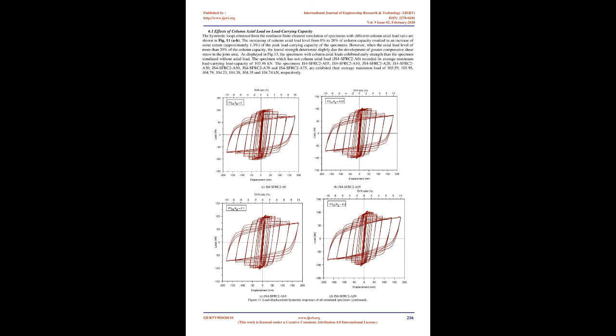Note, P is the applied axial load to the column. f'c is the cylindrical compressive strength of the steel fiber concrete. Ag is the area of the column. db is the diameter of the reinforcement bar. bb is the width of the beam. hb is the overall depth of the beam. bc is the width of the column. hc is the overall depth of the column, and Vf is the volume fraction of steel fiber. Note, 1 mm equals 0.0394 inches.